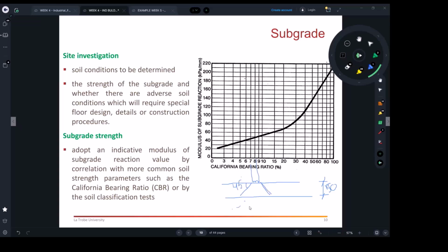Then it's going to get to the soil. So what we do, we divide that point load, say it's 10 kilonewtons, over this area, which comes from the 45 degree angle of repose distribution. Then after you find that stress, you just make sure where it's going to sit here. That's all you want to do.